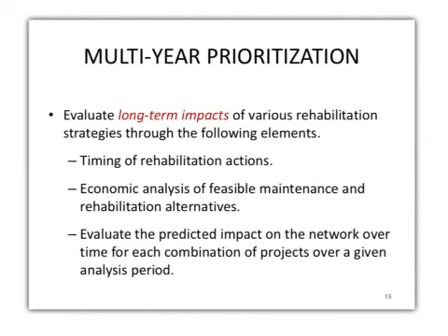So in the multi-year prioritization technique, we now need to evaluate long-term impacts. It's not just, once we put it in, what's the impact on the pavement health. It's really a long-term process of various rehabilitation strategies through the following elements. So while we're trying to study the long-term effect of any treatment, we need to look at these elements. The very first one is the timing of the rehabilitation action. When are you applying it?